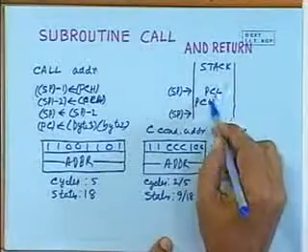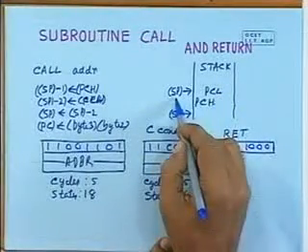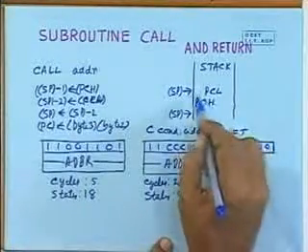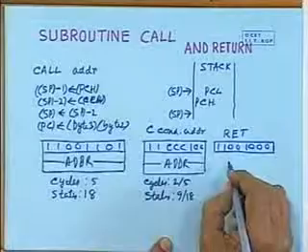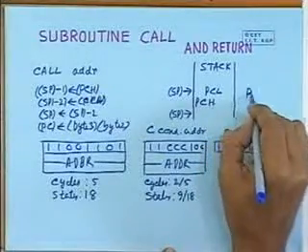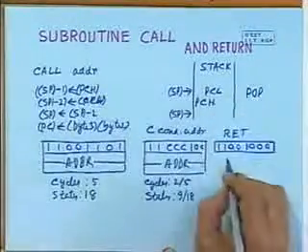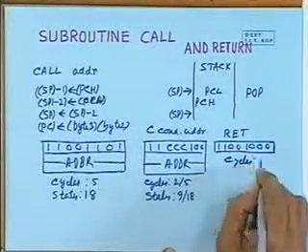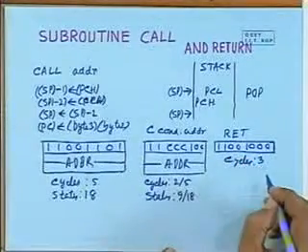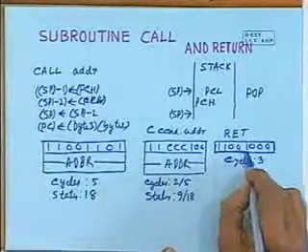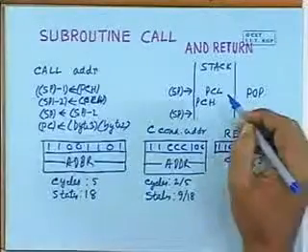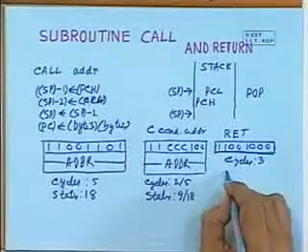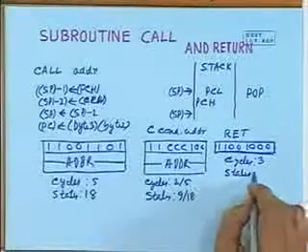But you see you don't have to specify the address, because stack pointer is already pointing to these two values. So it will execute some kind of pop operations, and the program counter will be loaded. Although the instruction is of only 1 byte, it will require 3 cycles. First one is machine fetch cycle, and following two are the read cycles from the stack, and it will be loaded into the program counter. So total number of states required will be 10.